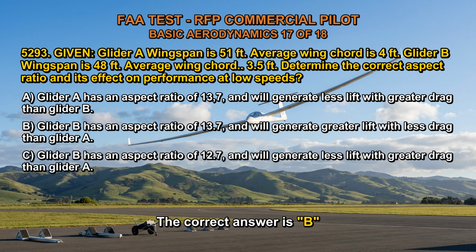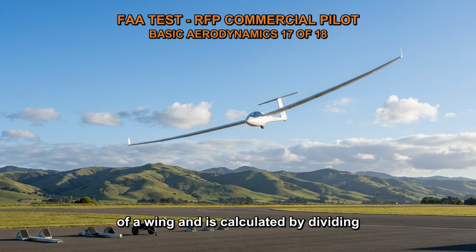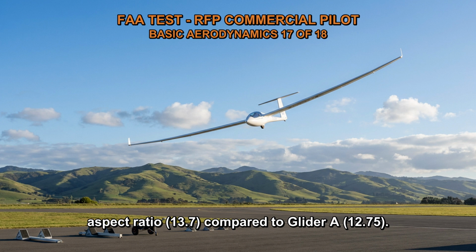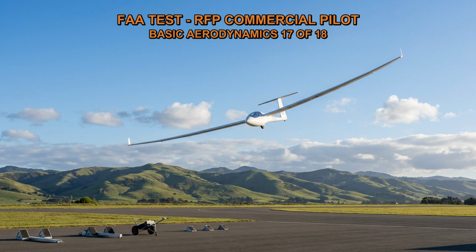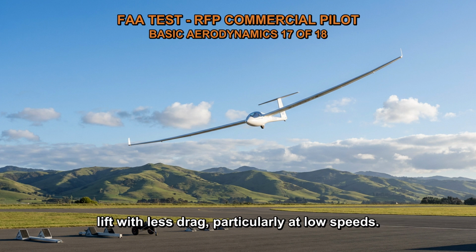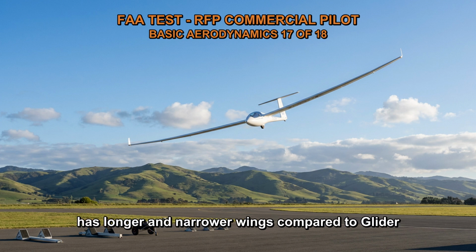The correct answer is B. Aspect ratio is a measure of the efficiency of a wing and is calculated by dividing the wingspan by the average wing chord. In this case, Glider B has a higher aspect ratio, 13.7, compared to Glider A, 12.75. Higher aspect ratio wings tend to generate greater lift with less drag, particularly at low speeds. Glider B's higher aspect ratio means that it has longer and narrower wings compared to Glider A.